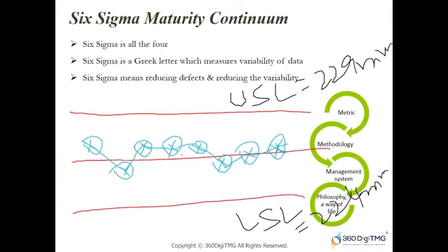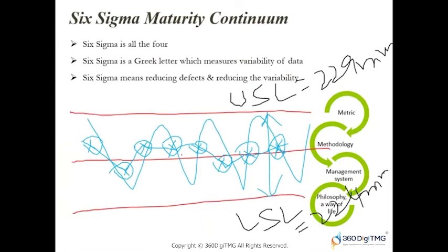Now can you tell me with a higher confidence, in comparison to the previous example, that the next cricket ball that is going to be manufactured would fall within the specification limits? I would agree that you would say that in this process, the next cricket ball that's going to be manufactured will most likely fall within the specification limits. I would say this with greater confidence. But in the previous example where the variation was high, you would say with less confidence that there is a possibility that the circumference of the next cricket ball manufactured would fall within the limits.